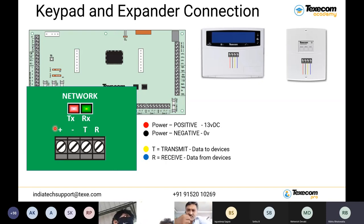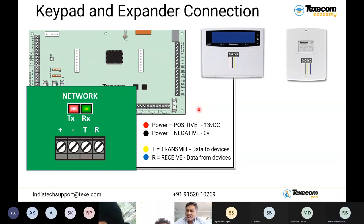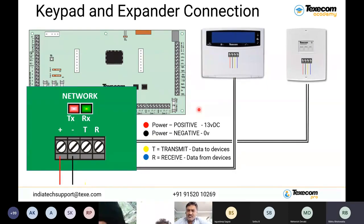Now on this network port, what all products can you connect? Number 1 is your keypad, and number 2 is your expander, the zone expander, which gives you 8 additional zones, right? In the keypad and in the expander, again we have a network port. You need to connect the wire as it is: positive to positive, negative to negative, transmit to transmit, receive to receive, like this.